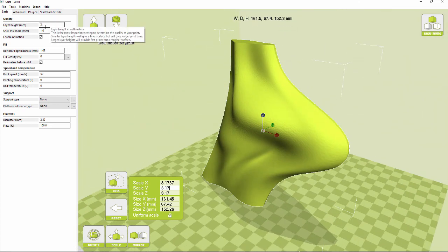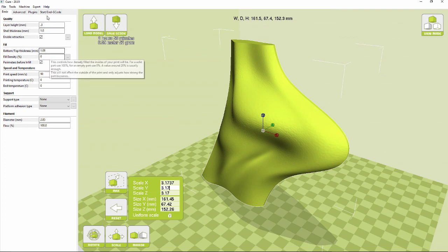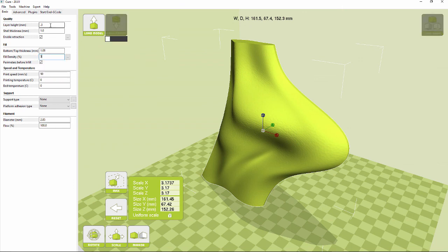And the primary modifications that I'm making for an architectural model like this: I really don't need any infill at all. Maybe I'll do a 5% infill. And then the default layer height is 0.18 millimeters. That's really the big time saver, changing this from 0.18 millimeters to 0.3 millimeters. If I drop that back down to the default 0.18, you can see this becomes about an 8-hour print if I remember correctly. And we really don't need that level of detail for an architectural study model.